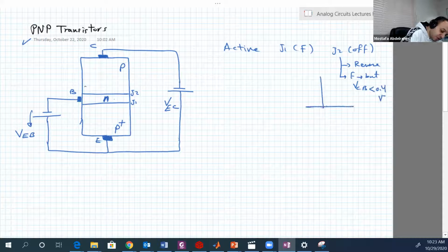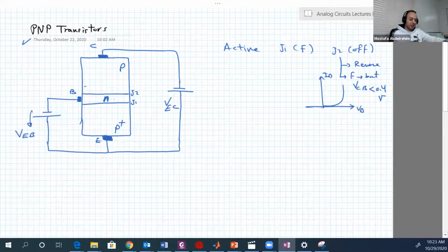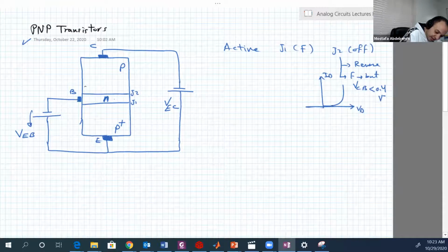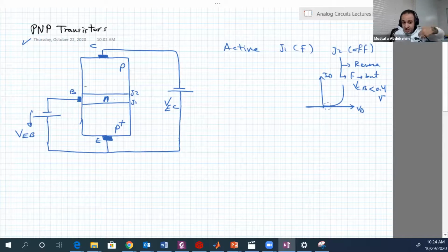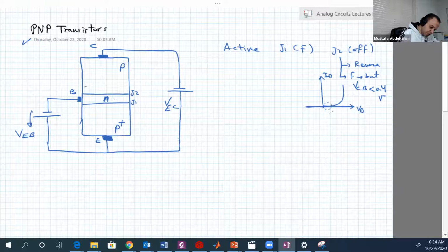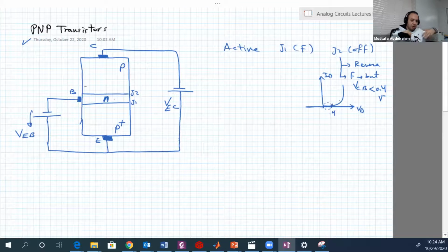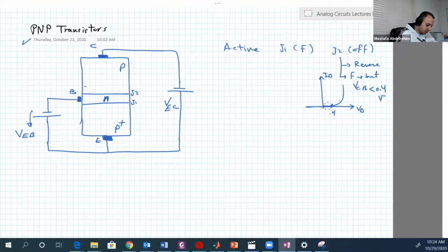Again, because here is the relation between the diode current, or any junction current, and the voltage across the junction. In that region, we are forward and the voltage is larger than 0, but the current is very, very small because it's an exponential relation. So we'll assume 0.4 is the point at which the current will start to have noticeable values.